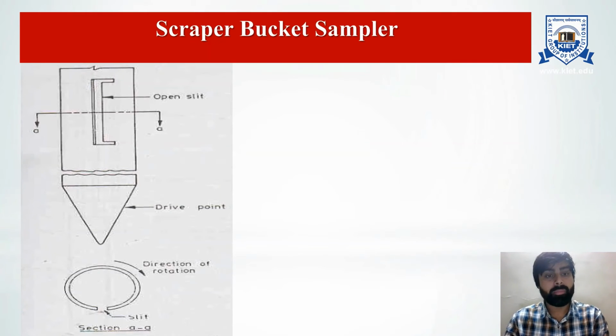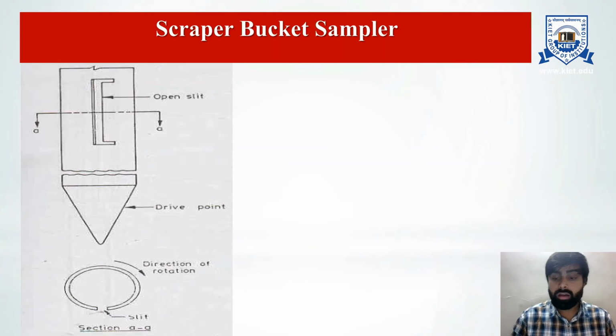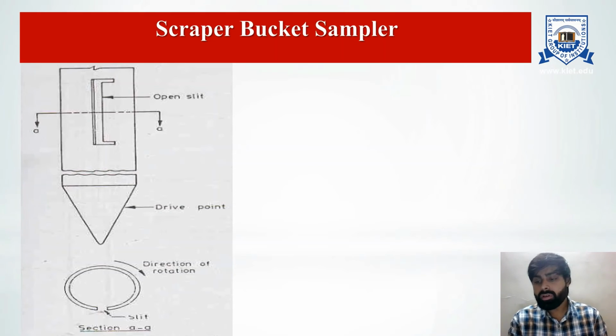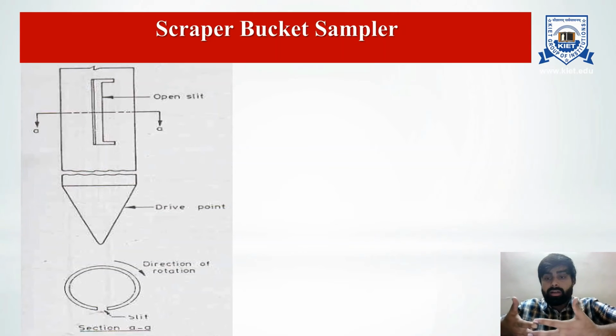Next is the scraper bucket. If a sandy deposit contains some pebbles, it is not possible to obtain a sample by a standard split spoon sampler or a split spoon sampler fitted with a spring core catcher. Then there are some pebbles.